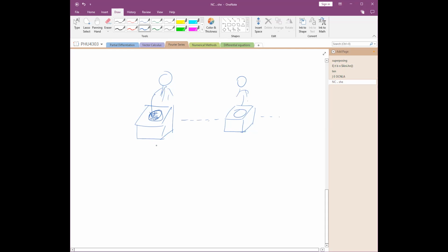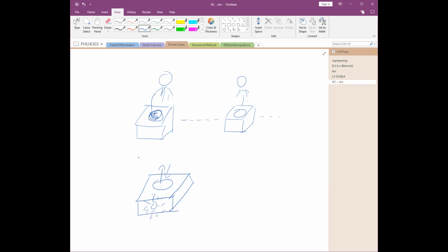So let's try to design a very simple part of this system. The idea is you have to have a single buzzer. Once the button is pressed, a light should switch on. Let's say this is the light. It should switch on, and even if you remove the hand, the light should be kept switched on. Now there are so many ways you can do it. You can do it using SCR, transistors, flip-flops, or a microcontroller, so many ways. But I want you to do it using relays.